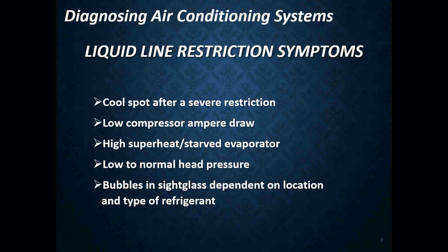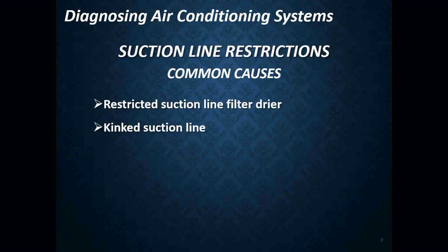You have to understand what you're dealing with when it comes to some of these things, guys. Now, the suction line may also be restricted in some cases. The suction line is much more sensitive than the liquid line because vapor instead of liquid is flowing through it. In order to understand what is happening inside a refrigeration system, you have to understand the refrigeration cycle. You have to know what the states of the refrigerant are throughout the entire system. You have to know the direction of flow